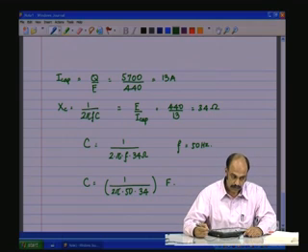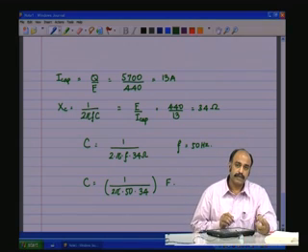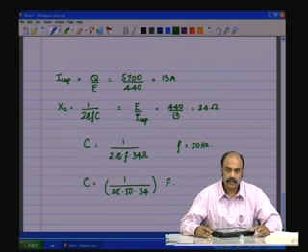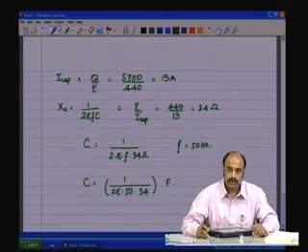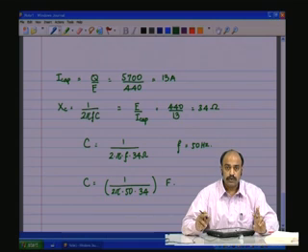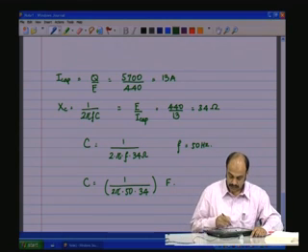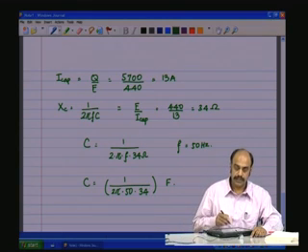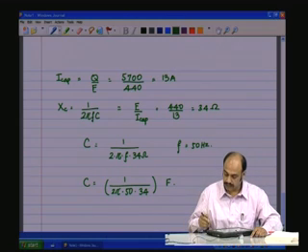So this is the way one goes about calculating the capacitance that needs to be connected to the three phases of the stator of the induction motor, if the induction motor has to be used as the induction generator supplying a standalone load not connected to another source, so that the reactive energy can be drawn from the capacitance, which can be used for maintaining the rotating flux.